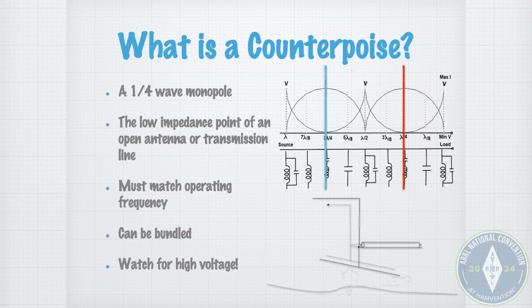So what you're doing is you're taking a high current point. You pump a lot of current into one side of that. The other side, the voltage flaps around because there's no boundary condition out there. It will radiate like a part of your antenna system, but it will try to stabilize that voltage near where you are. And this really does prevent RF burns. I've had the experience personally. But again, they have to be matching that frequency. But watch out for that high voltage. Be sure you fold them over and tape them on the end.